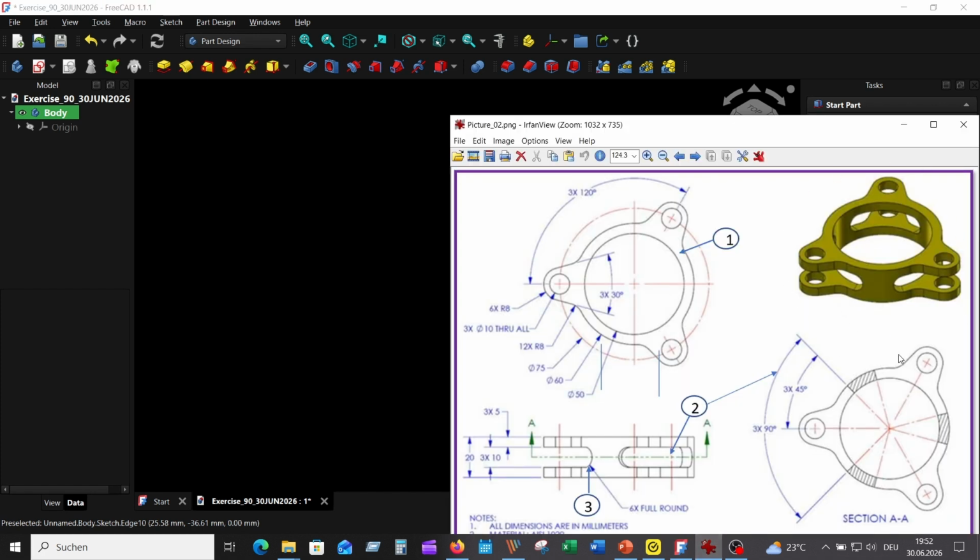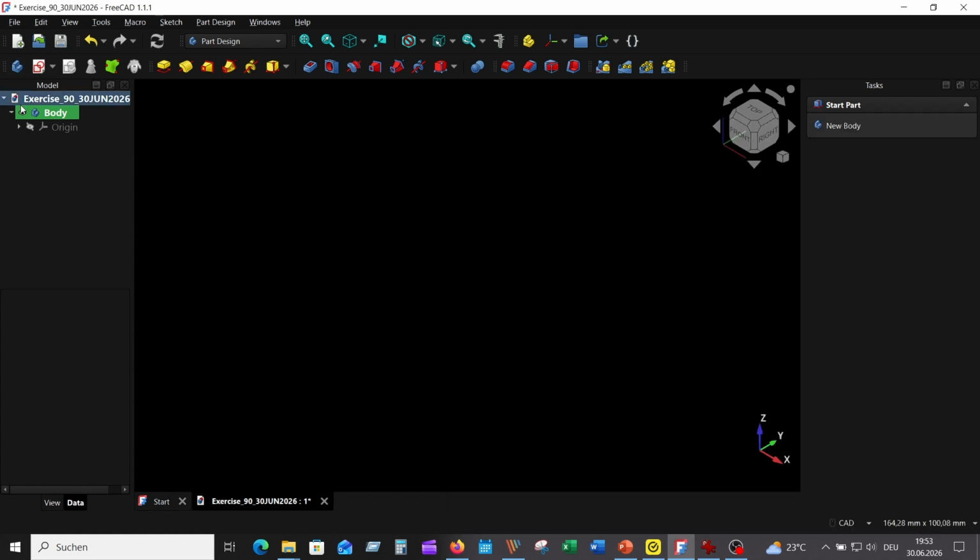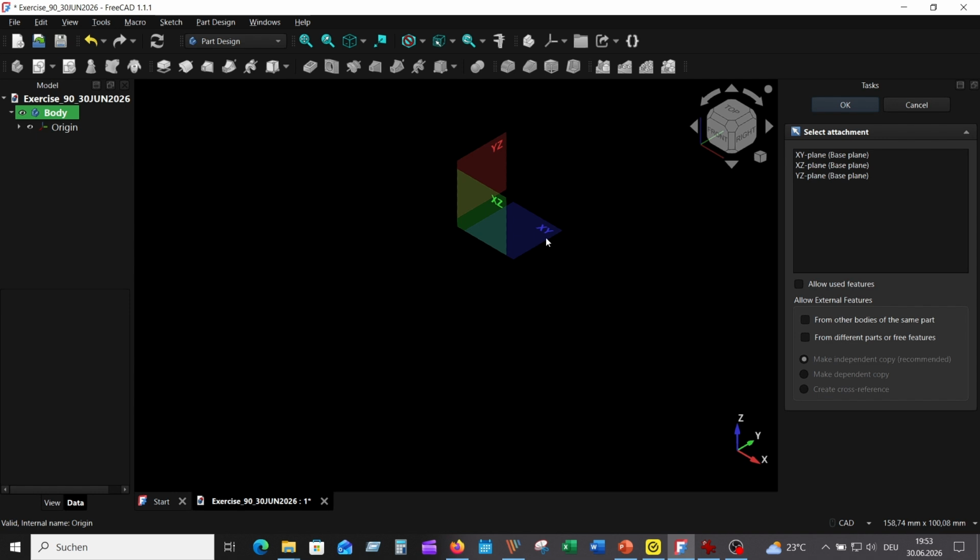We finalize this 3D solid part in 3 steps. In step 1, we sketch the profile of position 1 on the XY plane and create a solid part with the Extrude tool. Activate the Sketch tool and then select the XY plane.